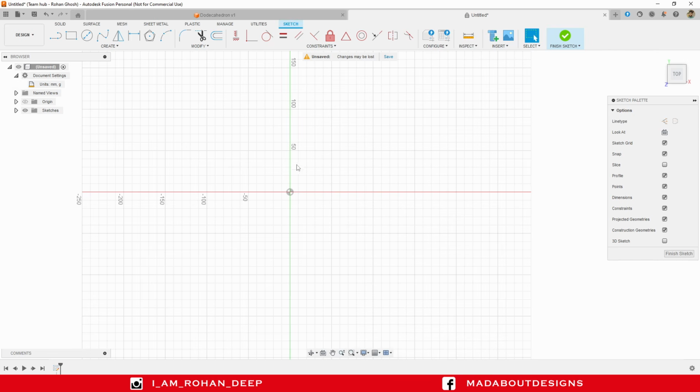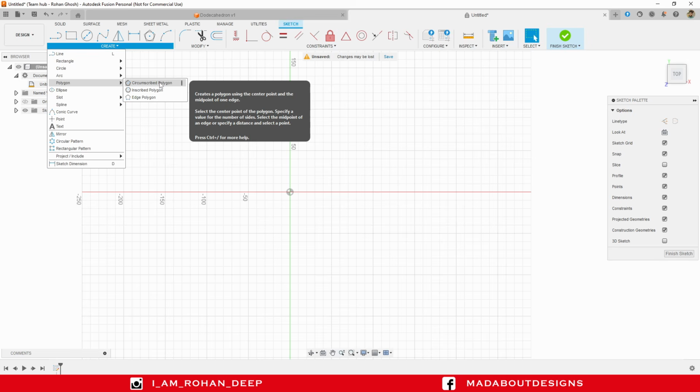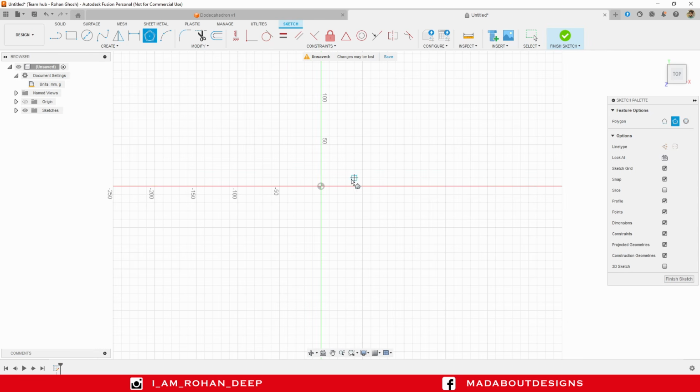We need one pentagon to create the complete sketch. To do so, go to Polygon and circumscribed polygon. You can also take inscribed polygon for this, but for now I am going to work with circumscribed polygon. Select the center of the polygon as the origin.